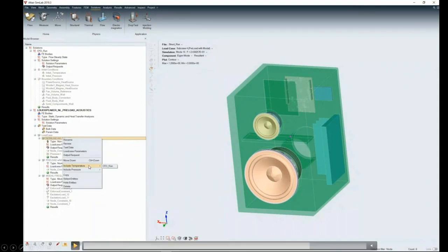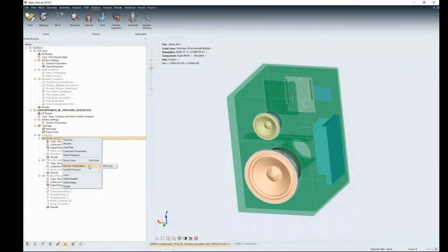Now, once you have the CFD analysis done, and then you want to do nonlinear analysis in SimLab, if you're doing a sequential coupling, it enables you to pick and say, hey, I want to take the temperatures mapped onto my structured mesh. I want to include pressures from the CFD analysis to my structured mesh. Those are taken as a preloading, or those could be taken as loads to solve any kind of analysis. This is pretty much done in SimLab pretty nicely and automatically, where the user does not have to worry about whether he has a mesh correct, whether it is different geometries, whether the CAD is okay, what are the coordinates.